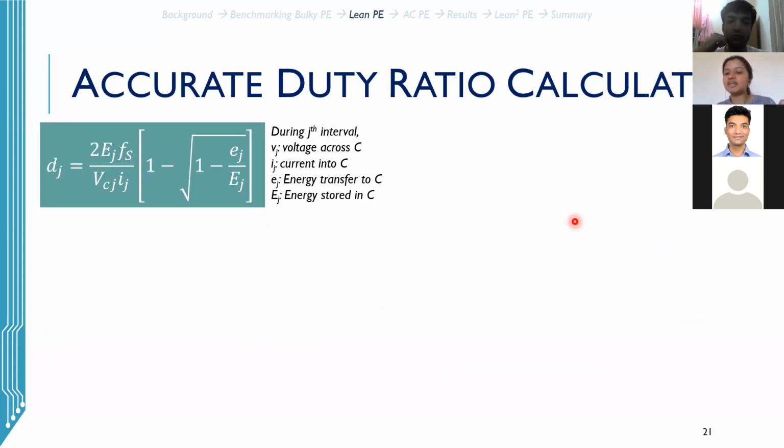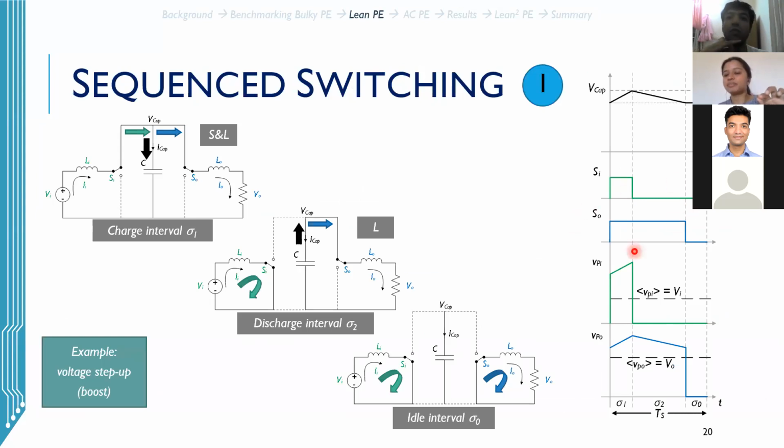While this is the DC to DC situation, we can extend it to AC cases. Instead of, say, space vector modulation, we can have a voltage and a current vector. We can select two vectors, implement the same idea of sequence switching, and go from there. Does it answer your question?